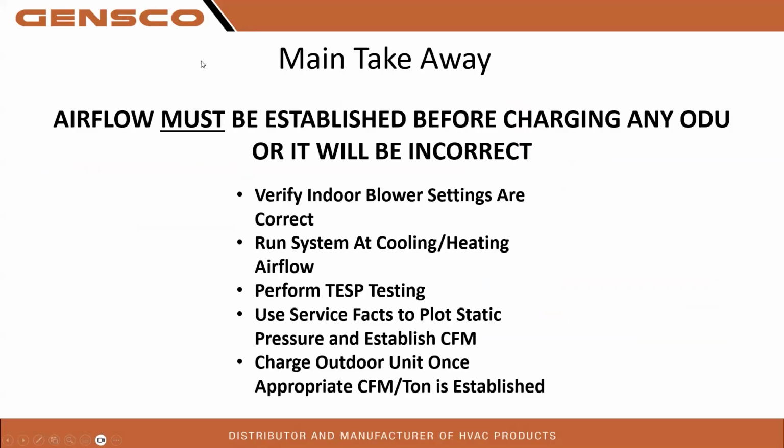So, main takeaway for today: airflow. It must be established and set before charging any outdoor unit, or it will be incorrect. I cannot stress that enough. If you do not move the airflow, we cannot move the proper refrigerant, which means we cannot have a properly sized, properly working system. You might have sold that customer a 3-ton, but are we actually running at 3 tons of capacity? Verify the indoor blower settings are correct.